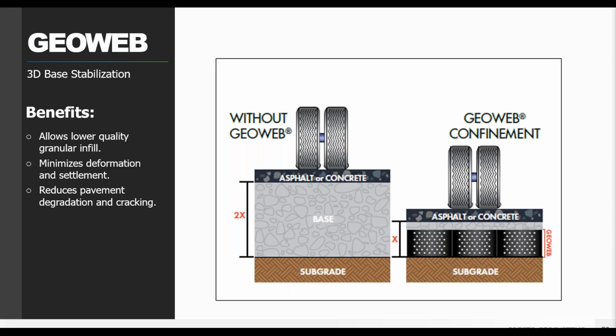And like I said, all those nice benefits still apply when it's used as a base layer rather than the surface layer. You can still use those low quality aggregates or sandy materials, so you don't need to bring in that difficult or expensive stone. And that stress reduction from the panels will still reduce the potential for deformation or settlement when placed over soft soils. So you're not going to see things like alligator cracking or wheel ruts or potholes. All of that stuff, it's not going to form at the surface because you have a nice strong base layer.